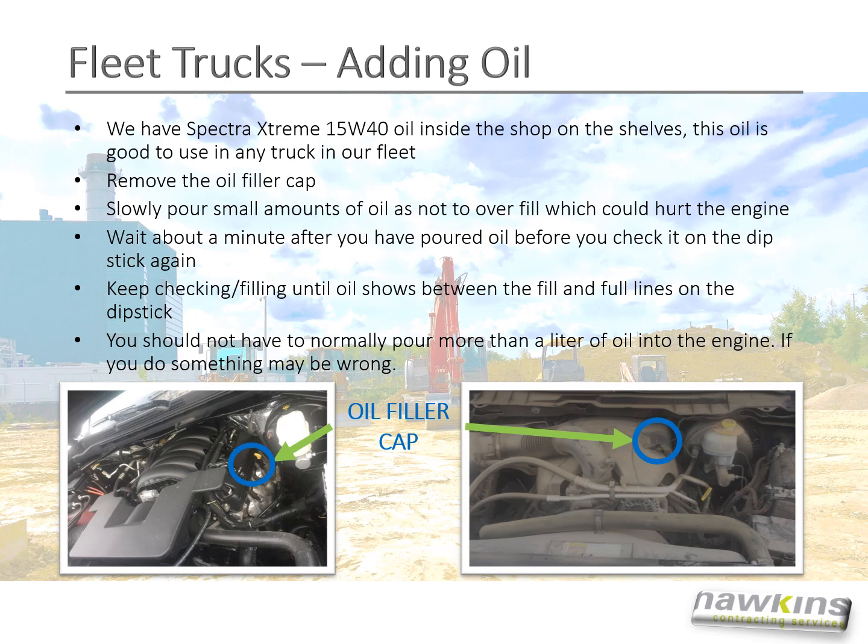Wait about a minute after you've poured the oil before you check it again on the dipstick. Keep checking and filling until the oil shows between the fill and full lines on the dipstick. You should not normally have to pour more than 1 liter of oil into the engine. If you do, something may be wrong.